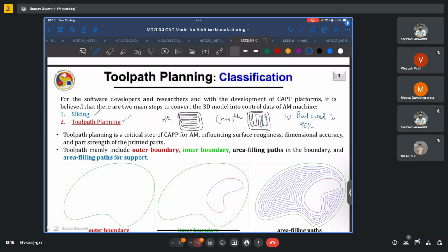And this is to ensure that there is good adhesion and good deposition of the first foundational layer with the build plate. Once that is deposited, often depositing successive layers on that initial layer is less of a challenge. Often the major challenge is depositing that first layer and ensuring that it adheres and sticks to the build plate.